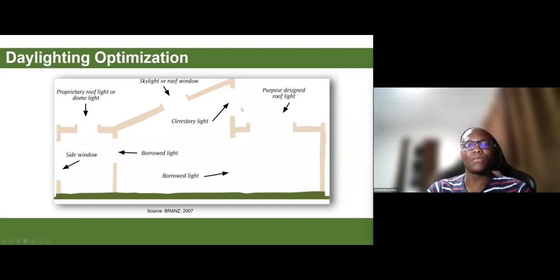The advantages of clerestory windows are that they are high up, and so it lets light from the bright part of the sky. They are unlikely to be obstructed by trees or other surrounding structures, can provide light to the darker part of your room. It can also give you some idea of what it's like outside, and it can also provide extra ventilation.